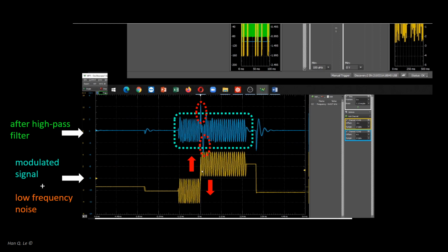However, what matters is the spike's total energy relative to that of a whole data pulse. Hence, as will be shown later, when the filtered signal is demodulated, the spike's total energy will be spread over the entire data pulse duration and its effects will be largely imperceptible, except for a statistical increase of what is known as the bit error rate.